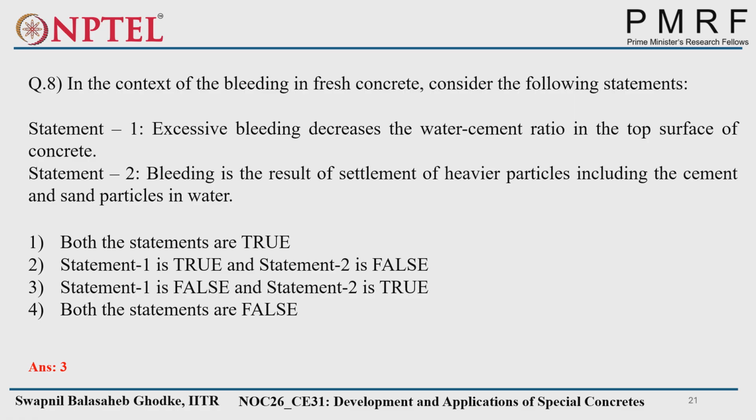It's not directly related to the superplasticizer. No doubt you are reducing the water content, but if you still go with higher compaction, or pour the concrete from a higher place, there is still a possibility that the available water will come to the top surface. So proper execution is more important.